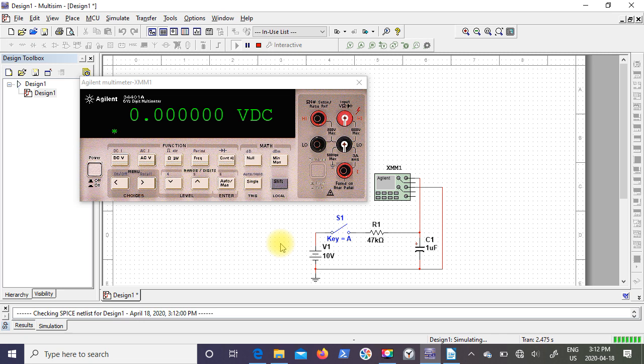So just a couple points about the simulation I want to mention. When you're looking at this particular circuit, if I close the switch, the capacitor should charge up to the total voltage. And you'll notice in this simulation, it doesn't. So sometimes adding a switch can stop your simulation from actually working. The other thing to note is, see down here where we have the time going?